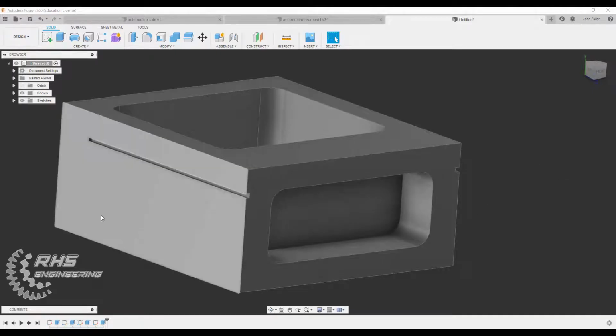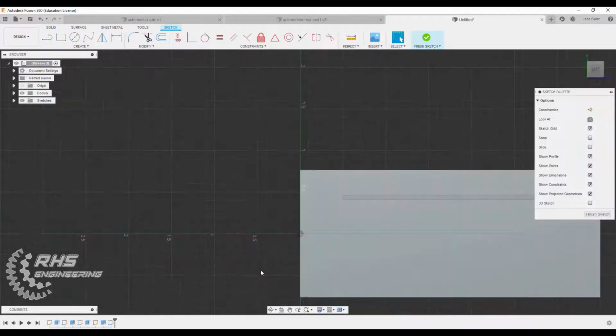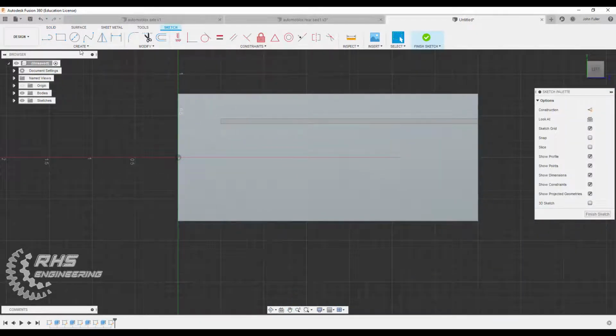All right, now we're going to make the axle holes. So we're going to click on this face and start a sketch. I'm going to come on up here to create, grab a point, and somewhere in this vicinity, right here, I'm going to just drop my point. I'm going to add some dimensions here now. From this side to this side, I want it to be 2, and then from here to the bottom, I would like that distance to be 0.3.